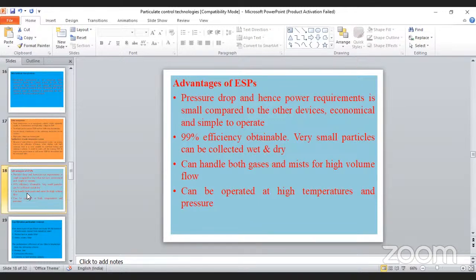After that, by natural gravity only, it settled down. But efficiency is okay. When we are operating at continuous flow, that also gives better efficiency, but this electrostatic precipitator can be used to settle down the fine particles. But a gravitational chamber cannot do this, because if gas density and particle density are both the same, it will not settle down. It goes along with the gas.